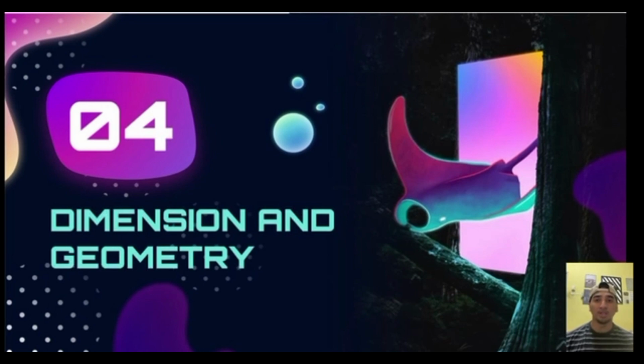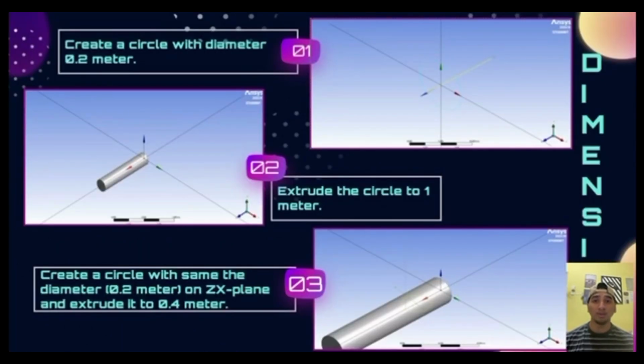Dimension and geometries. Before we start our analysis, we have to build our model. The first step is create the circle with 0.2 diameter. Second step is extrude to 1 meter. Third step is create a circle with the same diameter, which is 0.2 meter on ZX plane and extrude it to 0.4 meter.